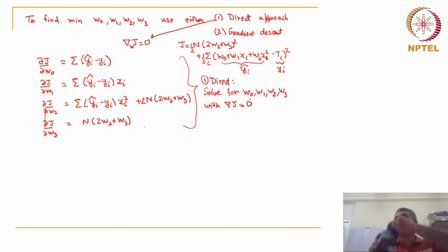But I will not do that. I want to show you a few things with gradient descent because that's what is general. Why? Because in this case, we took a quadratic equation. If you take quadratic, cubic, any polynomial, you will end up with a linear system of equations for this specific problem. In fact, even if you use the fin problem, it will not turn out to be linear because you have m square. You have the fin parameter, and that will make the problem non-linear. You will no longer be able to solve it like this.